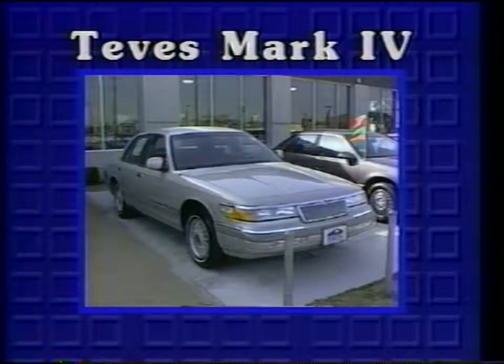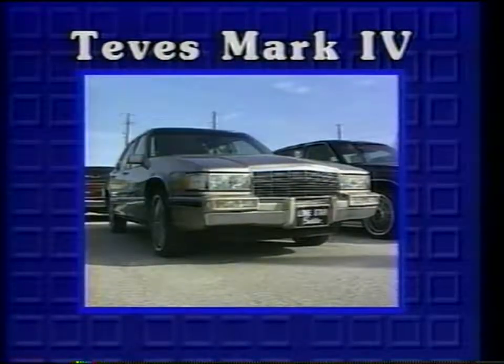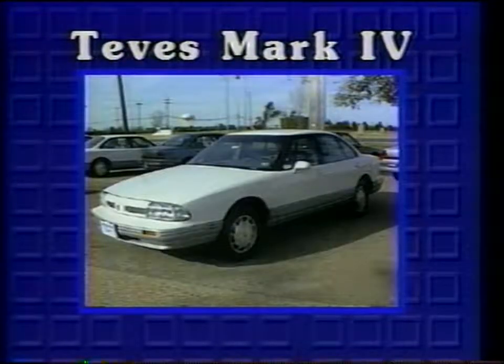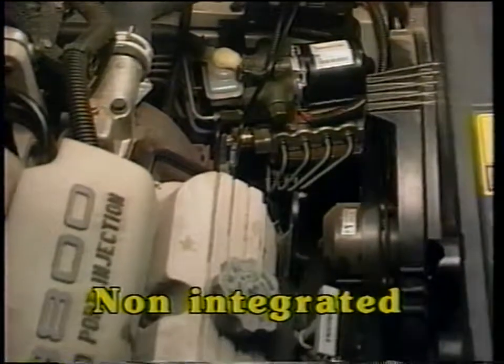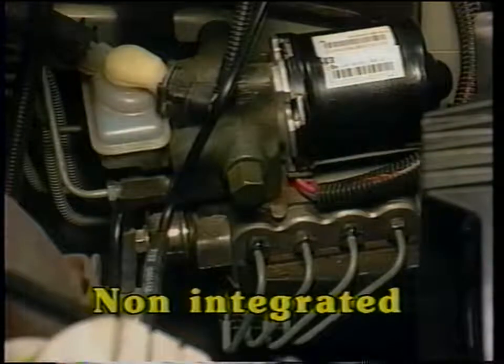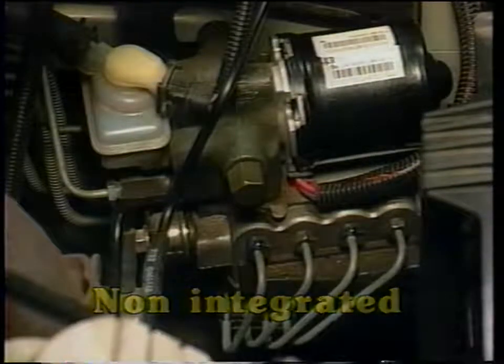and Grand Marquis. General Motors also adopted the Mark IV system in '91 for its Buick Park Avenue and LeSabre, Cadillac DeVille, Pontiac Bonneville, and Oldsmobile 98, 88, and Royale. The Mark IV system is an add-on or non-integrated ABS system that uses a separate hydraulic modulator and pump assembly in conjunction with a standard master brake cylinder and booster.